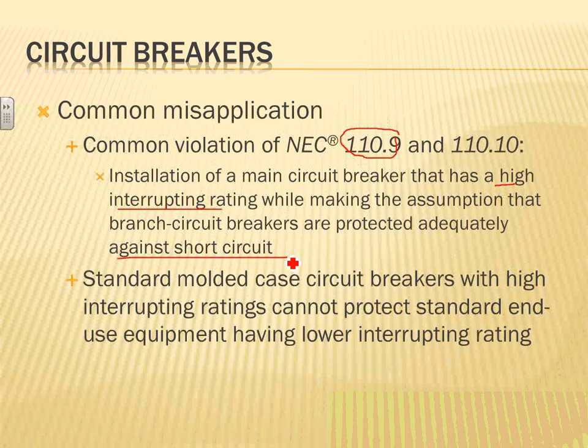Standard molded case circuit breakers with high interrupting rating cannot protect standard end use equipment having lower interrupting rating. This is the difference between interrupting rating and withstand rating. You have a good example because of this. You have PLCs, electronic equipment, VFDs. You put your circuit breaker there thinking that your circuit breaker will interrupt the short circuit, but will the VFD handle the short circuit inside it enough for the circuit breaker to interrupt it safely, or would it burn? So that's the whole idea. The circuit breaker will trip, but not before your VFD or soft drive or whatever burns.